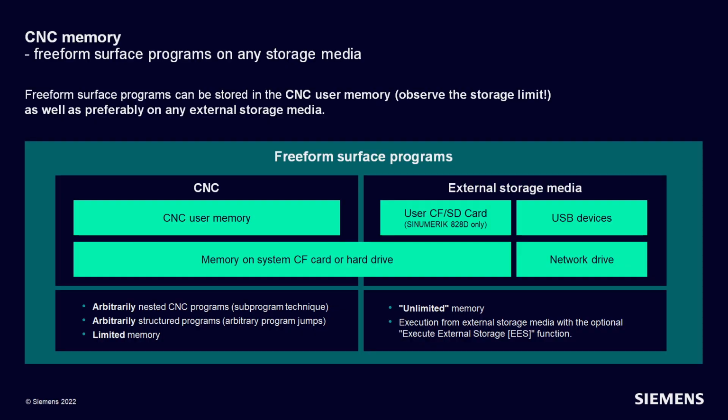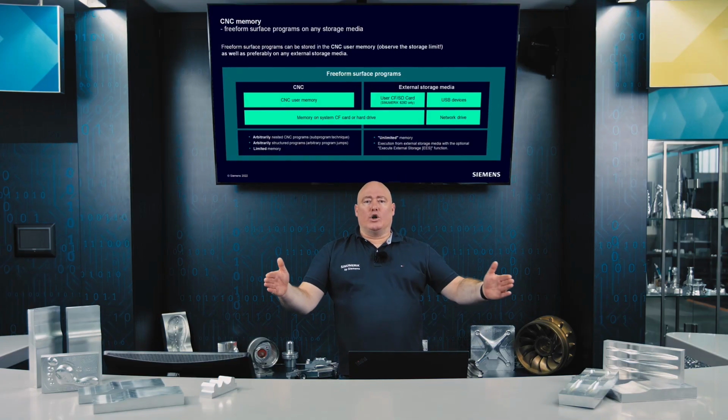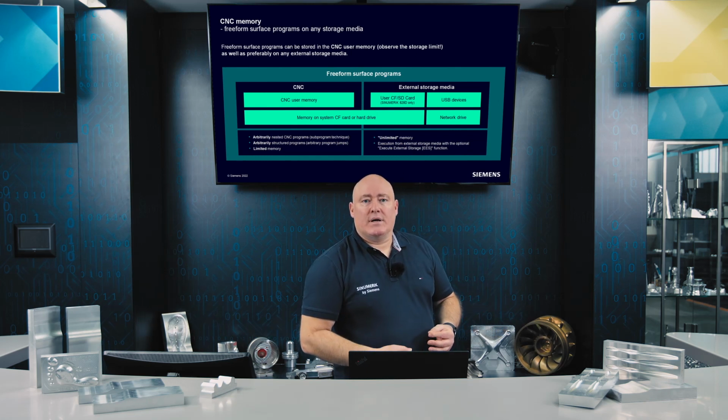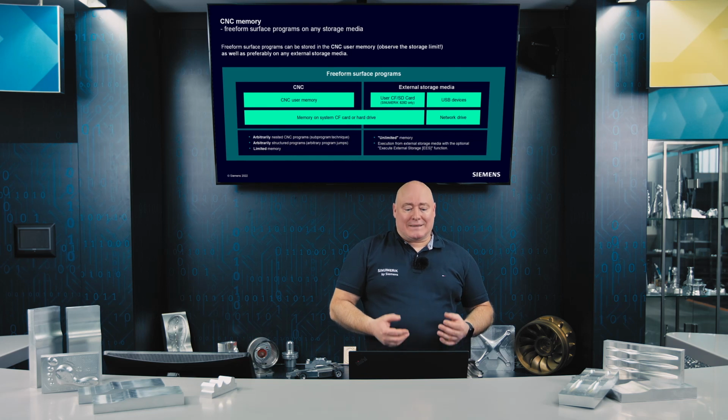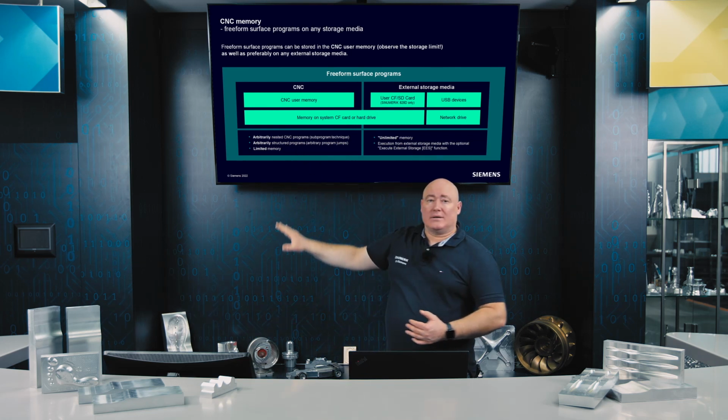NC programs, that is, the output from our CAD/CAM process chain, can be up to several hundred megabytes in size. It always depends on how big the component is, what technology I use in the CAD/CAM program, and of course, how fine the tolerance is when I create finishing programs. And if we're dealing with large programs, quite a few megabytes in size, then this will be too big for the CNC user memory because its storage capacity is limited.